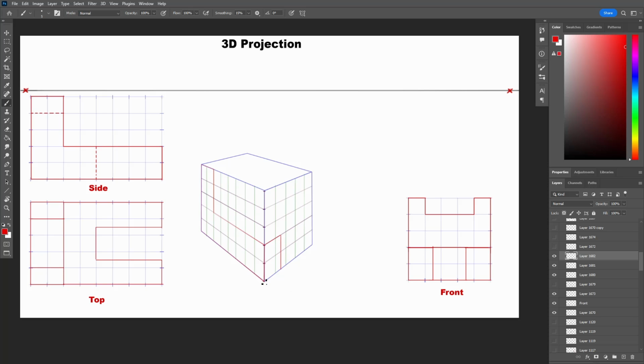If we look at the top view, we can see that there is a space in between, which is about 2 units wide. So let's stop the first part at 1.5 units, as we see in the top and front view, and continue the same line at the end, also at 1.5 units. From the top, we also have a space in between the top ends, which is 3 units wide. We can project the top for now all the way to the back, and move on to the base of